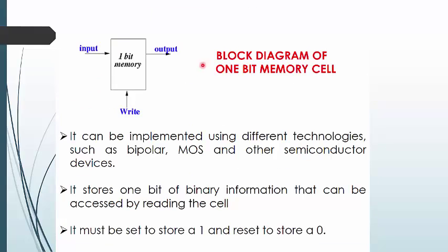Here we have the block diagrammatic representation of a 1-bit memory cell, where we can see there are two basic inputs: one is the actual input which is to be stored in the memory, and the other is the write terminal, which is the control input for that memory cell. This memory cell can be implemented using different technologies such as bipolar, MOS and other semiconductor devices.